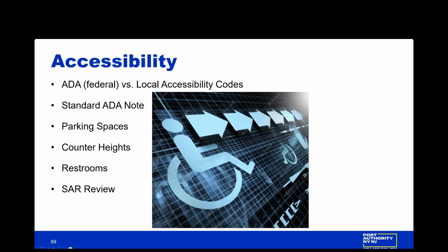And one thing I was thinking about for accessibility is what is often missed is the accessibility of employee workspaces. And another one could be if you're doing large restroom designs, you need ambulatory stalls in addition to the normal ADA stall. Next, please.